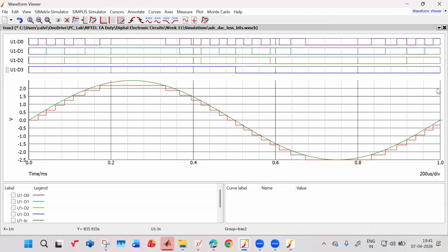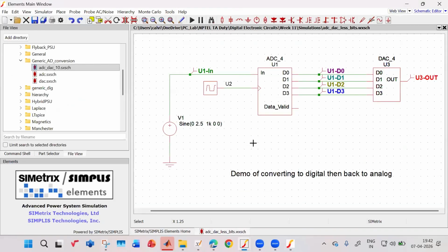In our lab, we use this test a lot. This is known as a loop back test. Okay. What does it mean? We have an input signal, which is a sine wave. It is a test signal that passes through my ADC, then that passes through a DAC, and I get an output again displayed. So the advantage of doing all this is, you know that your ADC is working, you know that your DAC is working and all. Okay, so you would need to test everything a lot.